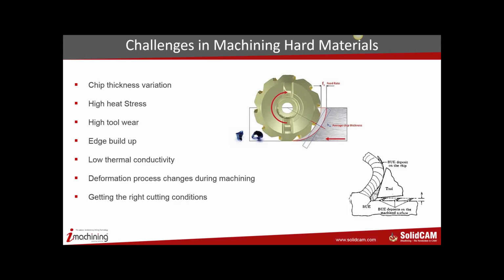You also have high heat stress because these materials have low thermal conductivity. Therefore, the stock doesn't absorb the heat, but passes this heat back to the tool. So they develop very high heat stress.